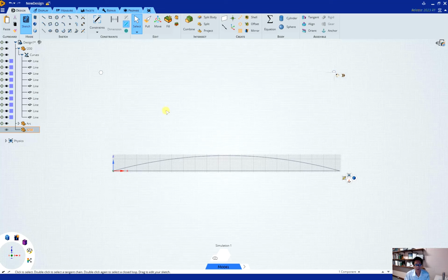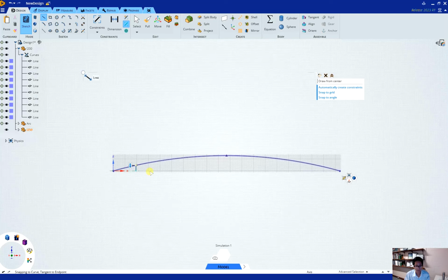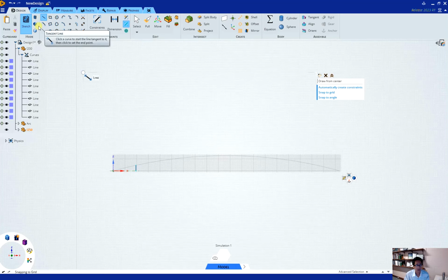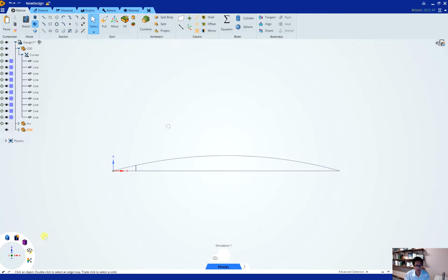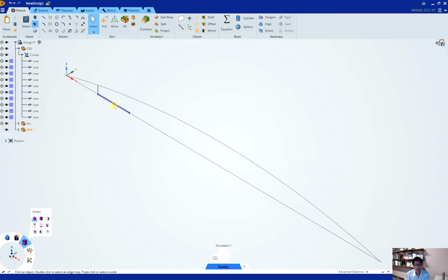Now I can start drawing it vertically up. So try to draw it vertically up this way. Line again. Now you can see that I couldn't find this one because I'm in another component now. So a good way to do that is you turn on the 3D sketching. And I often have the view isometric. So it helps me a lot in drawing. Now I can use this line. Now I can snap to any end.